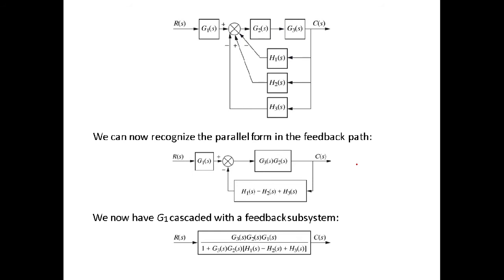Block diagram reduction technique is not unique, we can say that any physical system can be represented in a block diagram by one way, and you can simply find it in any other way. Whatever I have explained in the previous slide, the concept that we are using in this reduction is different. Here you can see that H1, H2 and H3 are in parallel. So first we are dealing with this part, and this will be easy for you. Whatever I explained to you was such a difficult way, the same way you can find the same transfer function, but the method will be different.